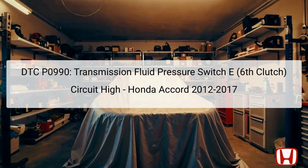The transmission fluid pressure switch plays a crucial role in monitoring fluid pressure, which is essential for the operation of the 6th gear. If this pressure switch fails, or if there's a problem in its circuit, the vehicle may only shift into 3rd or 6th gear due to a fail-safe mechanism, impeding normal performance. The switch's position is typically located inside the transmission assembly. Proper understanding and troubleshooting of this code are vital for restoring optimal function to the vehicle's transmission.